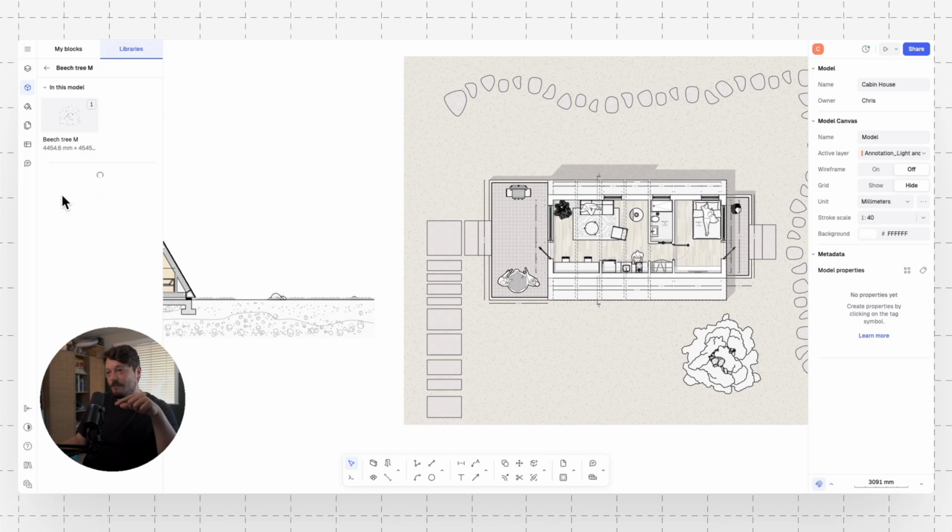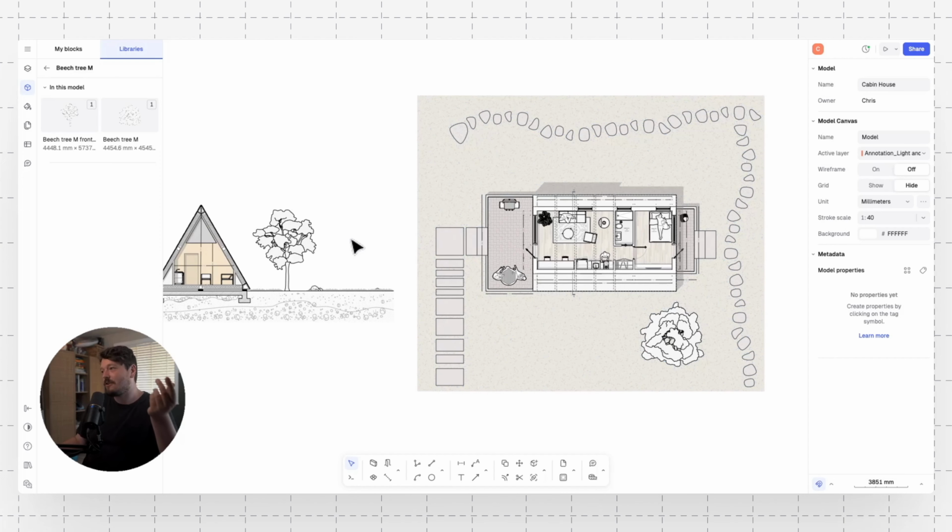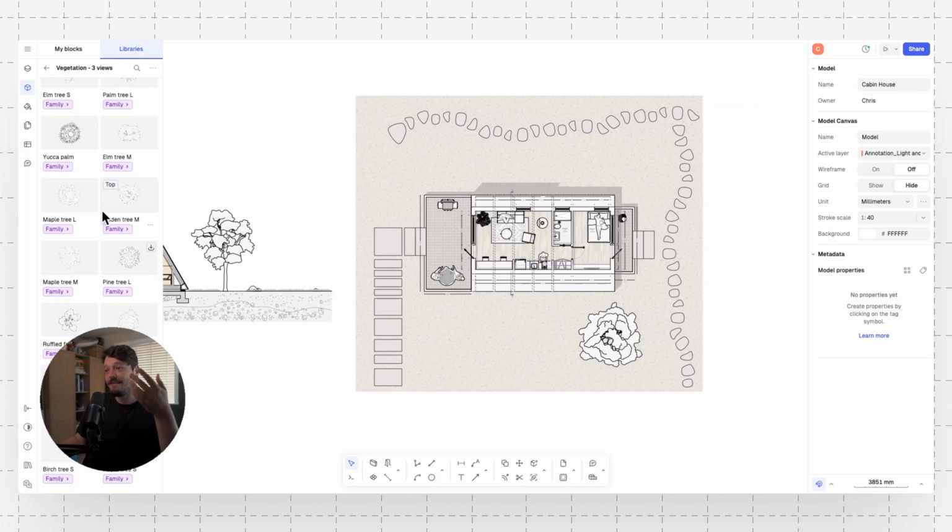Because we have this little purple area, I can see that I have an elevation as well. So I can click on that, drag that in, and I know that based on my section line, which is here, that tree is there, that tree is there. I'm even looking at it in the sort of correct scale. So those two things can start to correspond. So it's quick as just dragging things in and going from there.